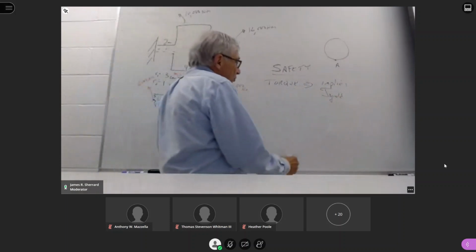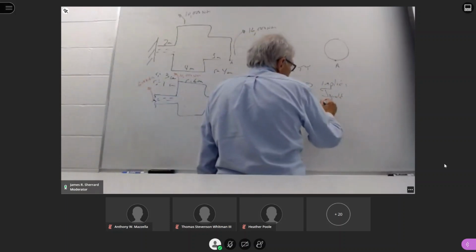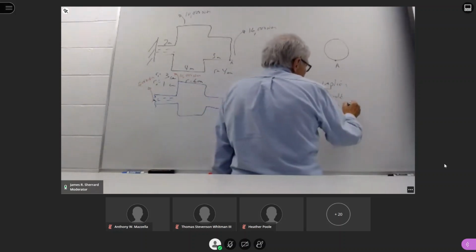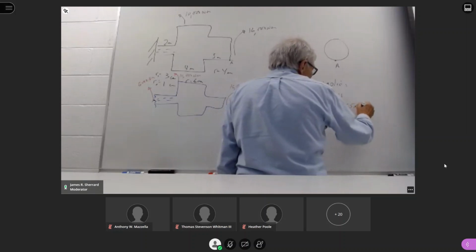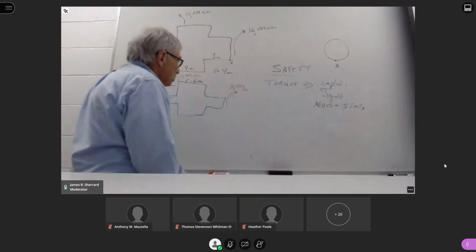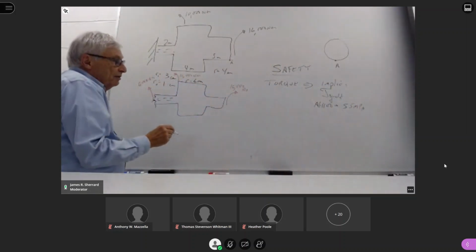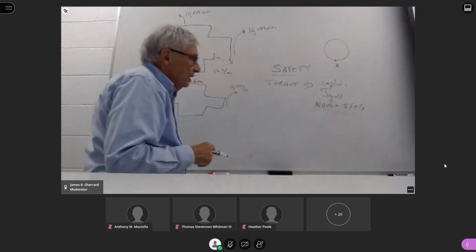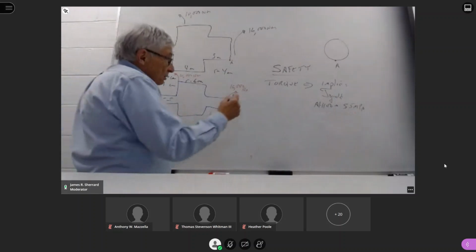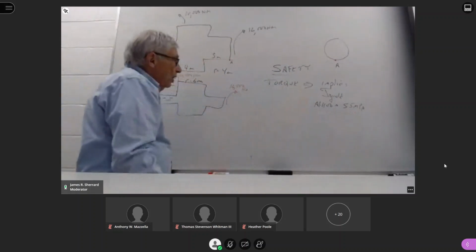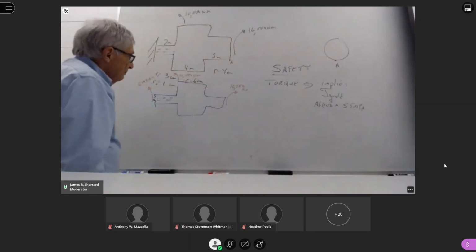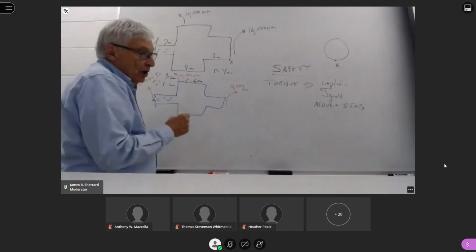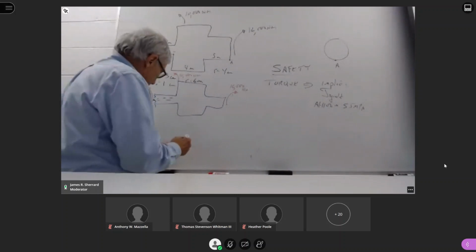Since we had aluminum 1100, we know that for aluminum 1100, that value is 55 megapascals. So since this entire thing is made out of aluminum 1100, whenever we exceed this, it's going to fail, and it will typically fail on the outer circumference of whatever section that we're looking at. Since we have 3 different sections, we're going to have to do 3 different calculations.